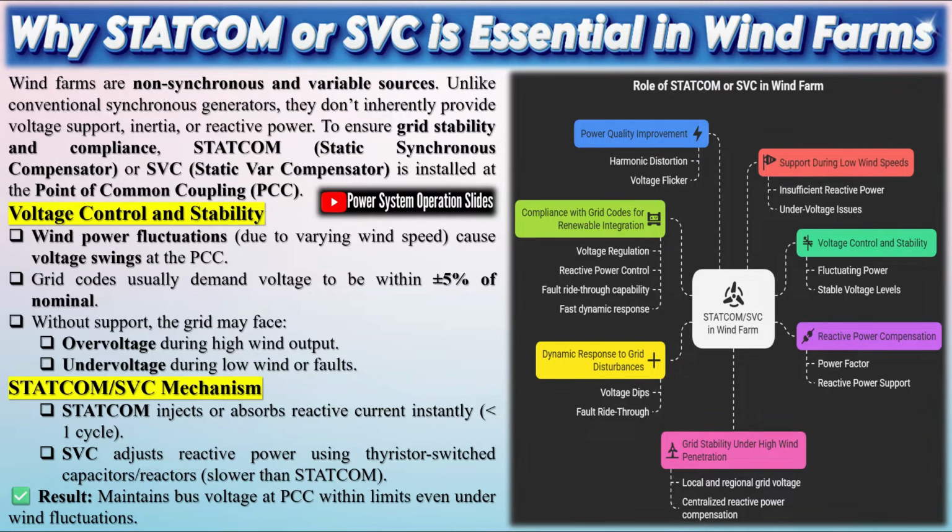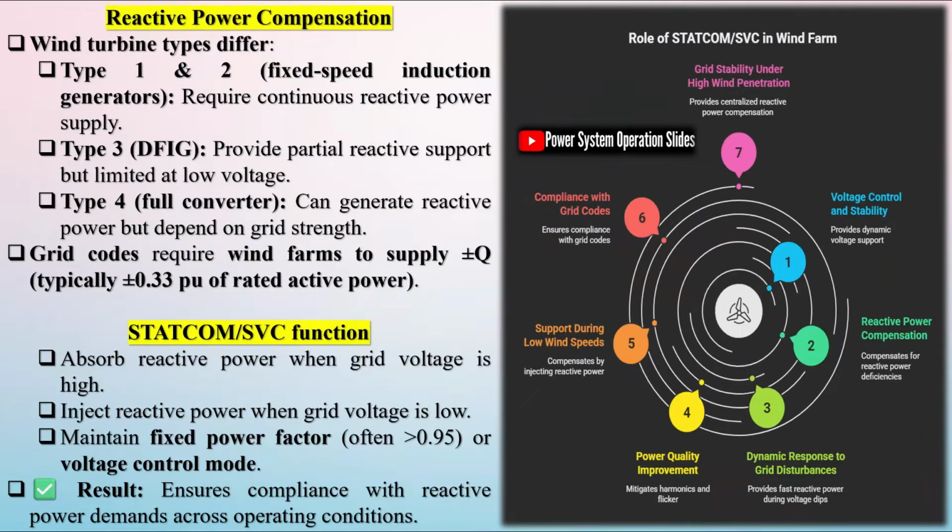Statcoms are versatile and can be deployed across a wide range of medium and high voltage applications. Their benefits are particularly evident in installations with solar inverters, wind turbine generators, transmission and distribution networks, hydrogen electrolyzers, railway electrification systems, and industrial setups with large motors or low power factor loads. In these environments, Statcoms help maintain power factor, support voltage stability, and reduce energy losses, especially where reactive power demand changes abruptly or in large steps.